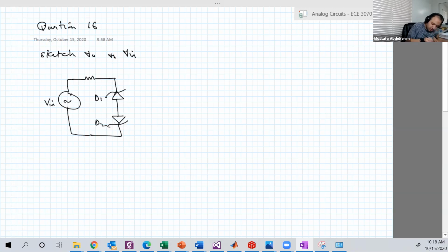This is diode 2 or Zener 2, whatever you call it. So V breakdown 2 is 10. So this guy here has a V breakdown equal to 10. Let's call it 2. And the first one has a V breakdown of 6.3. Okay. And in forward, when they conduct in forward bias, they both have 0.7 volt. And just a sketch of VO